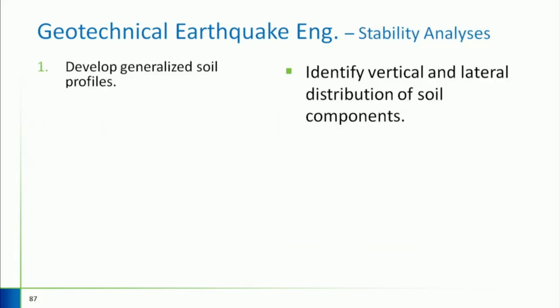Anyway, once you have all of these soil tests, in situ tests, your lab results, you have to develop a soil profile. It's a fictitious image of what's in there. It's always complicated, and we try to make it as simple as we can without missing anything. So there's actually a very big art to developing the soil profile, and we spend a lot of time developing that.